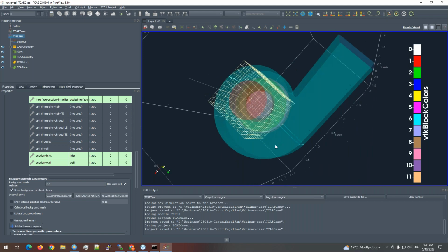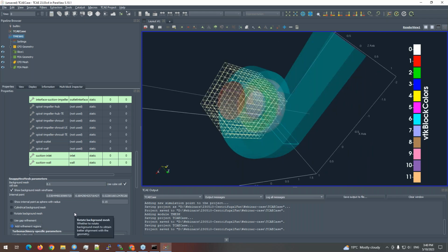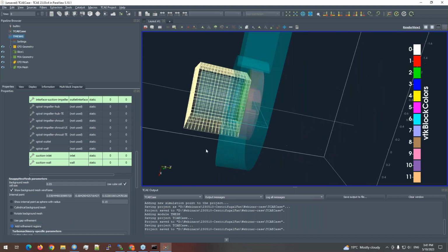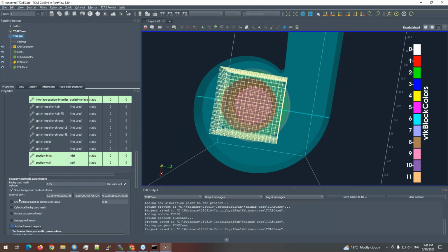Okay, I think it's too large. So now, yeah, playing with the mesh could take several hours. I would like to create some rough mesh on which the simulation will be fast, but also, yeah, we can't expect very good accuracy. So from the simulation time point of view, I would like to create as coarse a mesh as possible, but one which describes all the geometry parts with some degree of accuracy. So let's try to set 5 centimeters, a cube of size 5 centimeters, which will be okay, I guess.